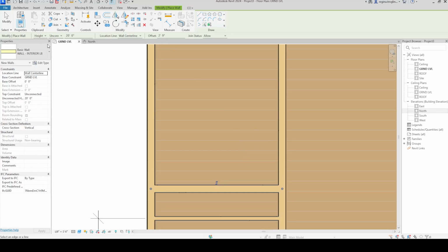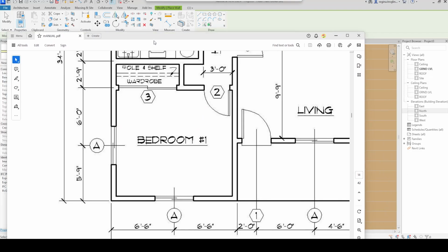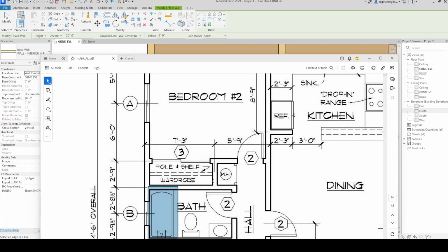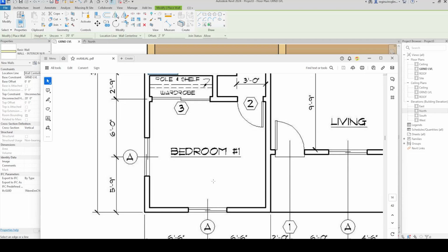Next wall up is a non-load bearing wall. And it is set at, so that's 2'9.5" and 2'8.5", but this is a bathroom. So this tub makes this bathroom a little bit funky. So let's go from the opposite side. It's the same pieces.